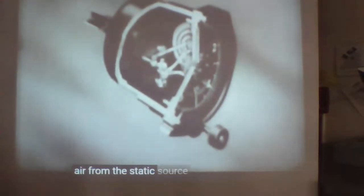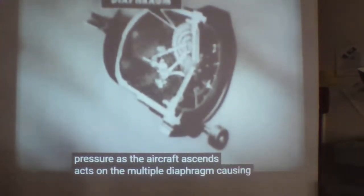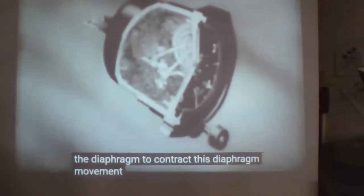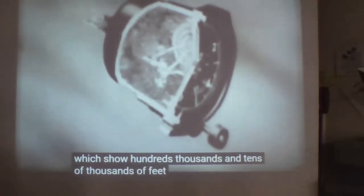Air from the static source of the pitot-static system enters the aircraft instrument case. Decreasing atmospheric pressure as the aircraft ascends acts on the multiple diaphragms, causing them to expand. Increasing pressure, encountered as the plane descends, causes the diaphragm to contract. This diaphragm movement is transmitted by multiple gears to the hands on the dial, which show hundreds, thousands, and tens of thousands of feet.